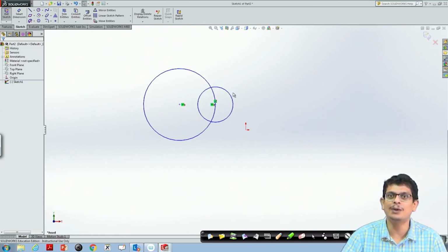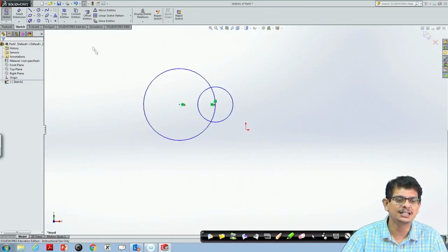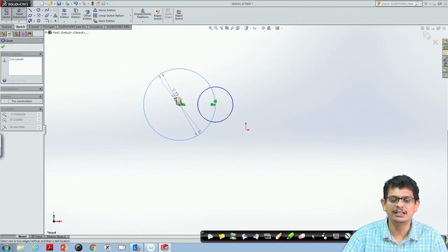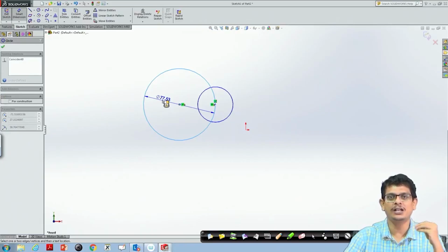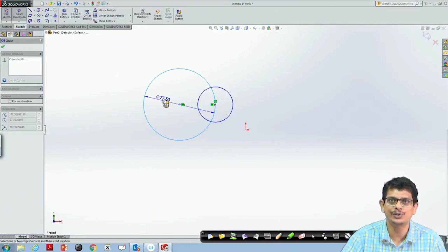Now, I would like to use smart dimensions to realign these numbers. So, pick smart dimension, click that circle, then it shows something like diameter of that circle. If you recall from our earlier lectures, whenever we use something like diameter, the symbol phi comes into picture, and the same symbol, same terminology here on the software also we are seeing. Now, I would like to give internally the diameter.